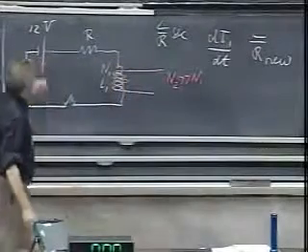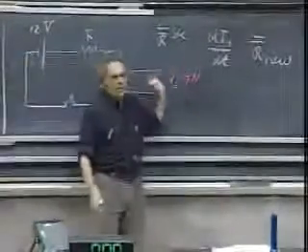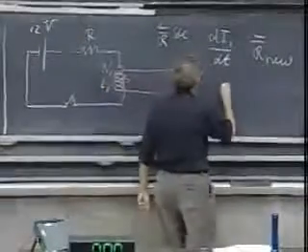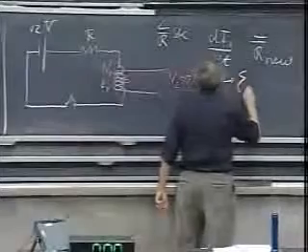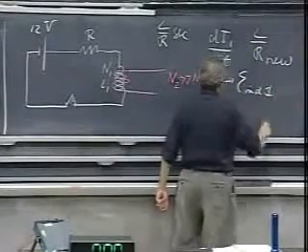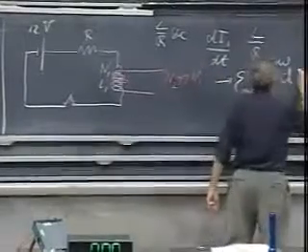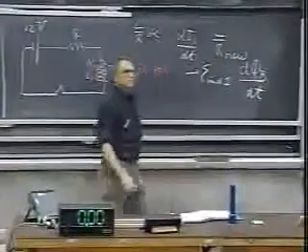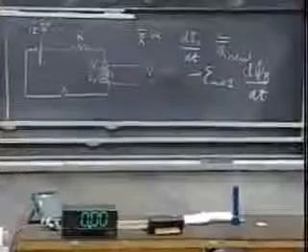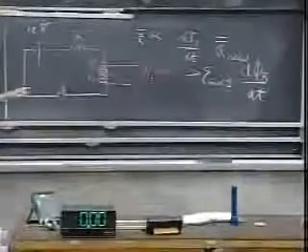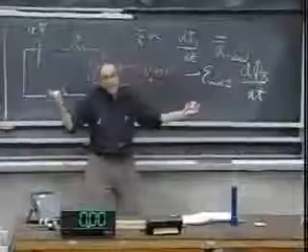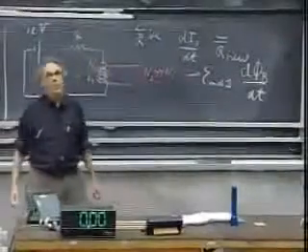With a 12-volt battery, you can easily get several hundred volts EMF now, because the dI1/dt will of course create an EMF, an induced EMF in that circuit, because you get a dΦ/dt. You get an enormous change in the magnetic flux here, which is directly coupled to the current. And that induced EMF could be several hundred volts.